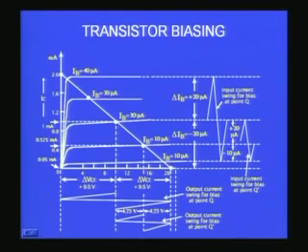milliamperes. And therefore that, when passed through an RC of 10K, can give me 0.5 into 10, 5 volts plus or minus 5 volts. So that is what is shown here. I can get a swing of about 10 volts about this quiescent point when I have this point.